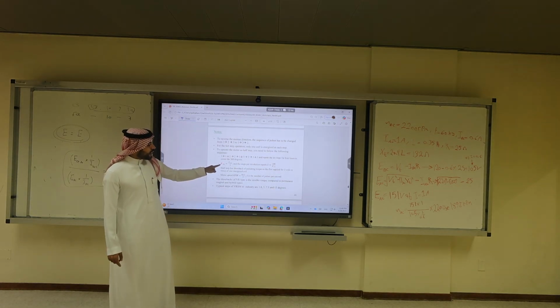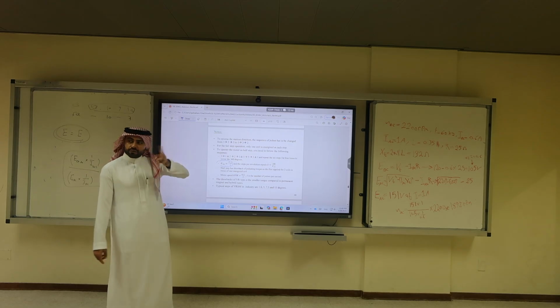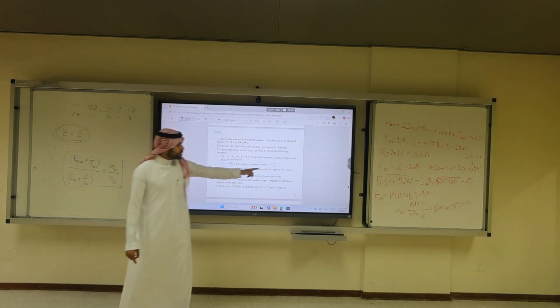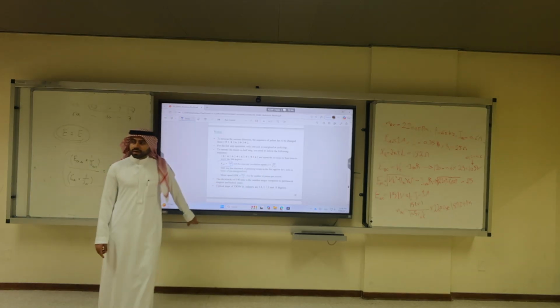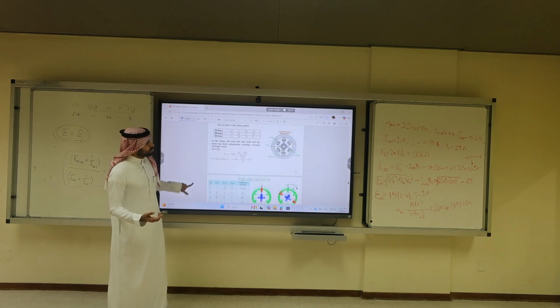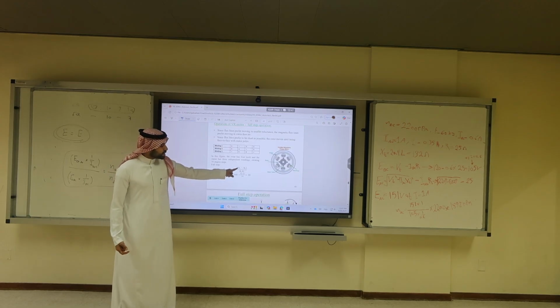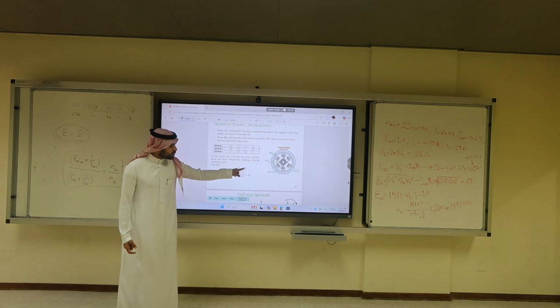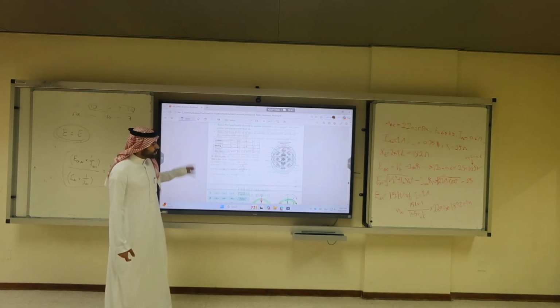And clearly the half step angle is half of the full step. So if the full step angle using this equation is 360 times the difference between the number of teeth over the multiplication between them, it is 30, and the half step is 15.